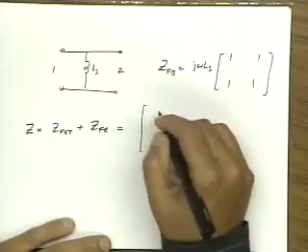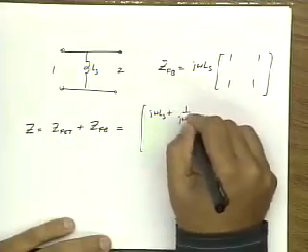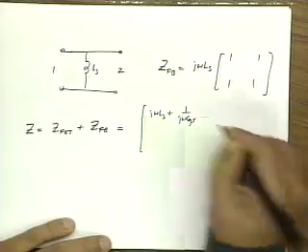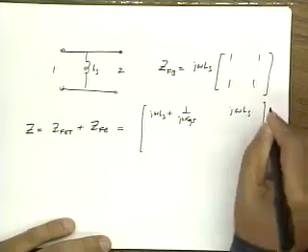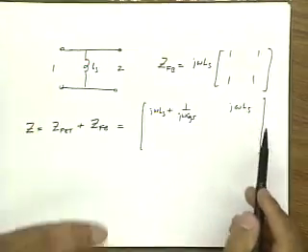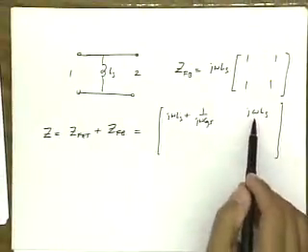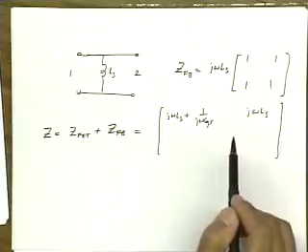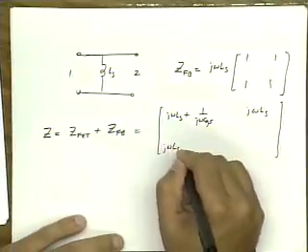And so we can all add in this class hopefully, Z11, Z12, and notice that the series feedback actually introduced feedback, I should say. It introduced feedback. Without LS, Z12 was equal to 0, but now because of the feedback we have a finite amount of Z12.